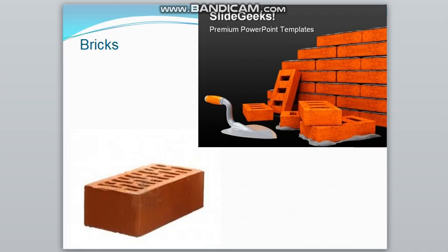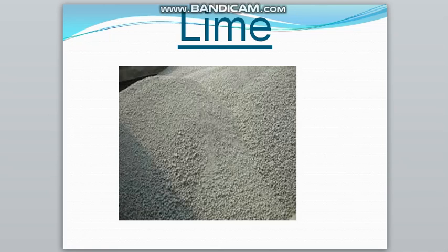Whereas another test is the efflorescence test according to Indian Standard 3495 part 3. So these are the three important tests: dimension test, water absorption test, and efflorescence test, which are performed mainly on the bricks. These are all about the bricks. Next we are discussing the lime.